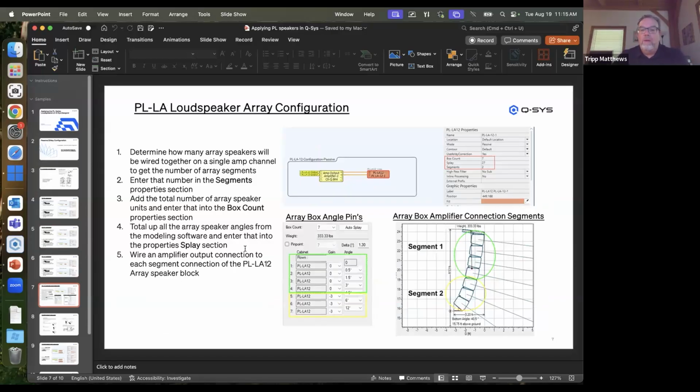They will come in and wire exactly the same, biamp or two-way or passive. But what you really need to know is when you're building your arrays, we need to know 2 main things. How are you powering the amplifier on these arrays? How many amplifier channels do you need? The other is, what is the actual splay break that you're bending your array?